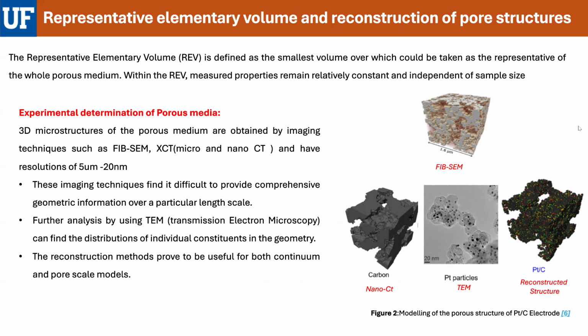Using the FIB SEM and the nano CT, we are able to effectively model the pore scale in greater detail, but it lacks much more important things such as the individual constituents present in the porous media, such as platinum and the carbon. So further analysis by TEM actually provides us the constituents and their geometry. This is effectively done to recreate the porous media for better understanding of the phenomena occurring at that scale.